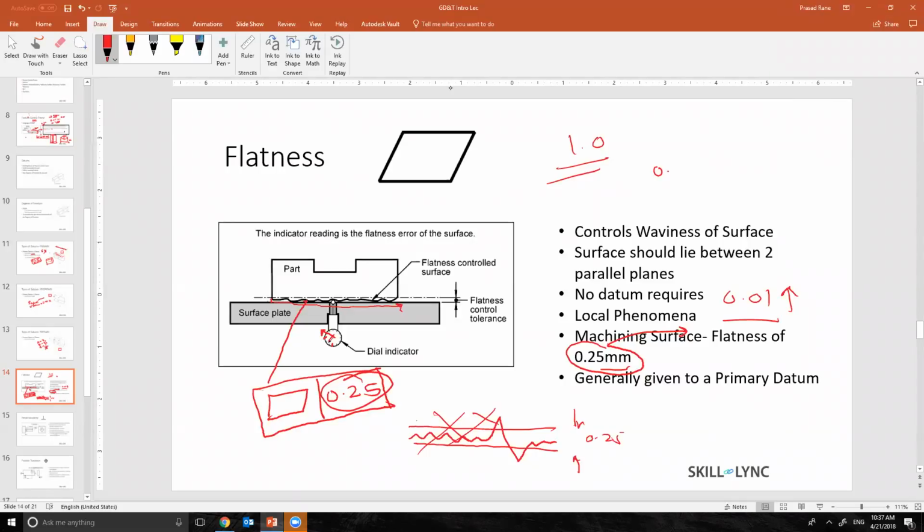All right, perfect. So the next question is from Kawaljeet. Is it necessary to have 0 degrees of freedom? Because at the end, the machines have some degrees of freedom. Right. Again, it depends on part to part. You are right, Kawaljeet. There are some parts which don't need to constrain all 6 degrees of freedom. Let me give you an example.